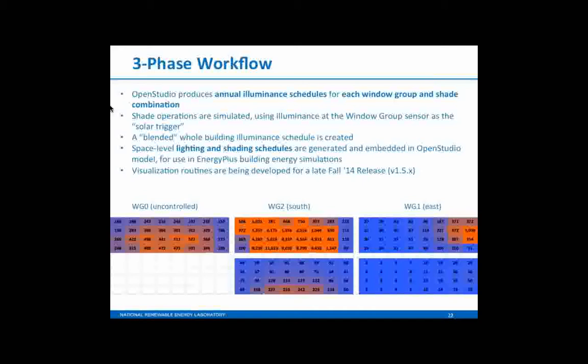The second window group, this row is for the shades up, this row is for the shades down. Again, you can see dramatically different results here. Here, we've got lots of direct sun splashing in through that clear south window. Users are probably going to lower the blinds or do something. So the reality is probably somewhere in between these two, really, for a good design, and this is how you figure that out. So this is showing the energy from that same window, but with that Venetian blind lowered and the slats set to block all the direct sun, so just a little bit filters in. Really only significant amounts right by the window itself.